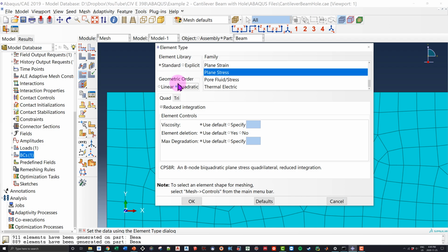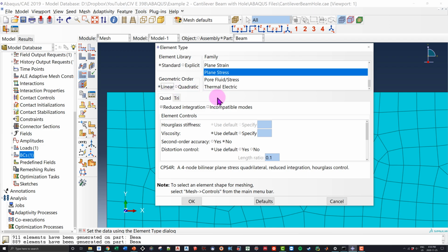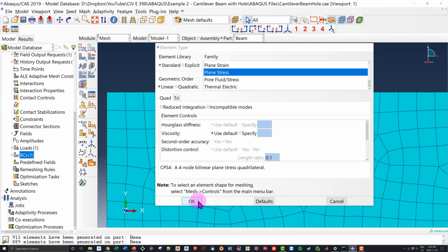Now, just like the step incrementation, you guys are running linear elastic models. Therefore, you actually don't need crazy elements, anything like that. So we're going to keep it linear. But one of the things you can do to help increase the accuracy, if you want, is just click off this reduced integration. The integration in ABAQUS is done using a Gaussian scheme. What happens is we actually consider more points if we disable this reduced integration. So this will help the accuracy of our solution, but of course, this will require more computation time. So I'm going to switch it off because these models are actually fairly quick.